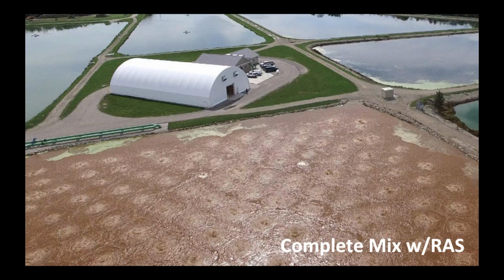And oftentimes they'll get massive dumps of dairy waste on their front doorstep, and it'll just come into the plant. It goes right into the lagoon. And what I've been told by the operator is, yeah, we get this dump at like 4 a.m., and it looked like the DO dropped maybe about 1 or 2 milligrams per liter, but then we were good, and that shows you how much it can absorb. So these are very popular for industrial wastewater treatment.